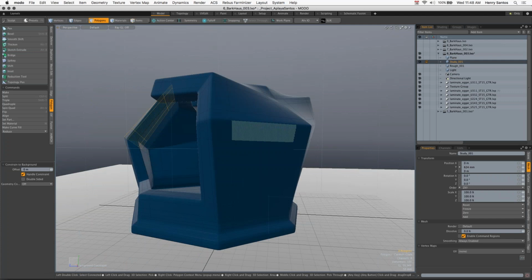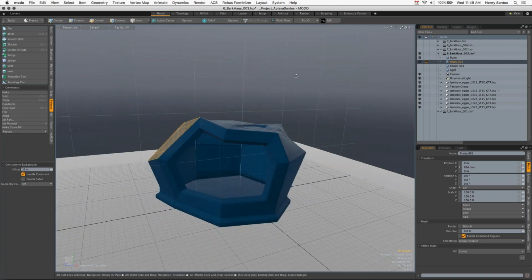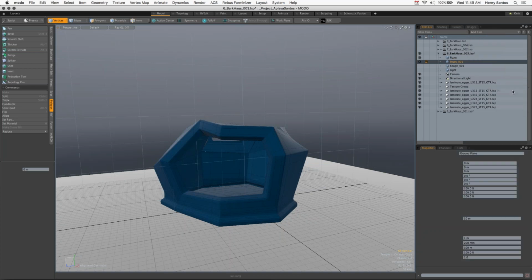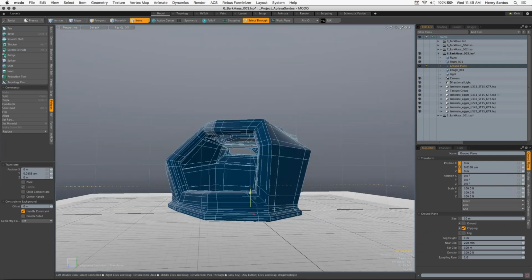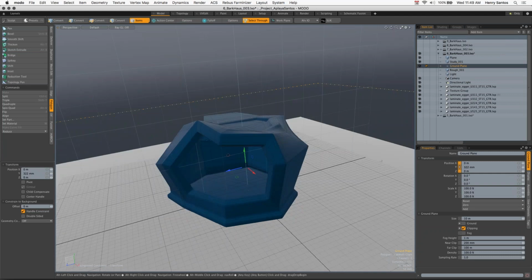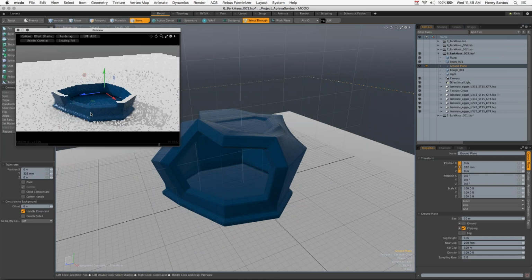Now, I'm not going into how to do that right now, but one way, since MODO isn't really a CAD program in the way we're used to CAD programs. For me, when I say CAD, I'm thinking architecture CAD, not necessarily AutoCAD, but more Vectorworks, where we used to produce 2D drawings. But you can add what's called a ground plane, turn it into a clipping plane, and bring that up to a cut height. Okay, so that'll cut it. And nothing really happens until you look at it in a preview window. And now you have your cut plane cutting across. And this is just visual.